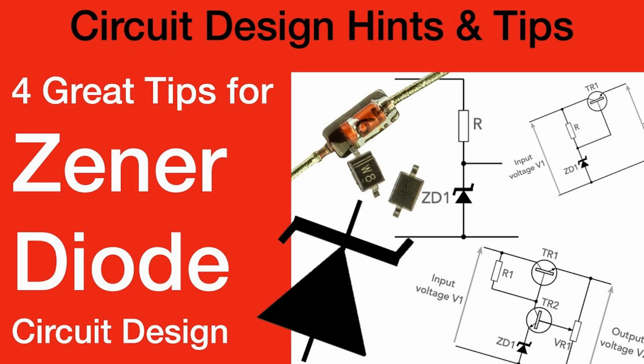Determine the load current. Identify the current required by the load. Choose Zener current. Select a minimum Zener current to ensure the diode operates correctly in the breakdown region. Choose a standard resistor value close to 280 ohms, such as 270 ohms or 300 ohms. Circuit diagram.